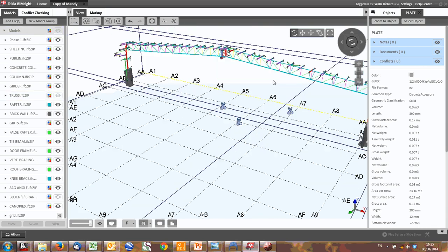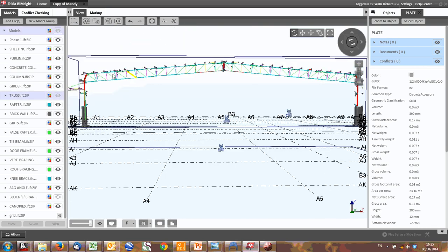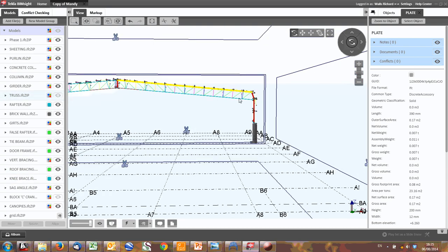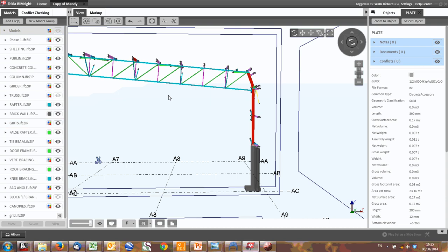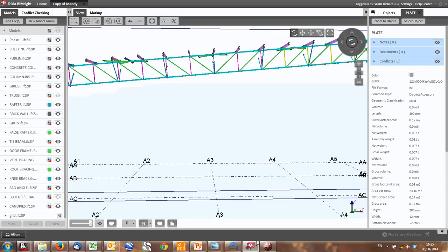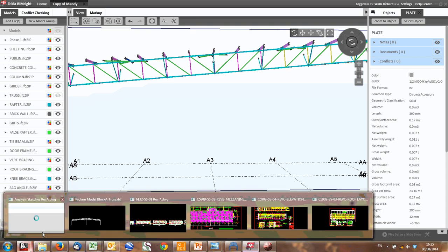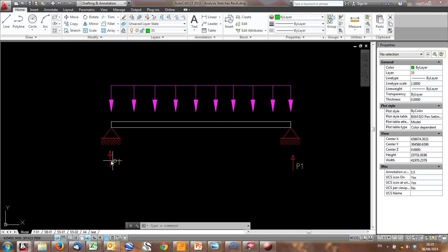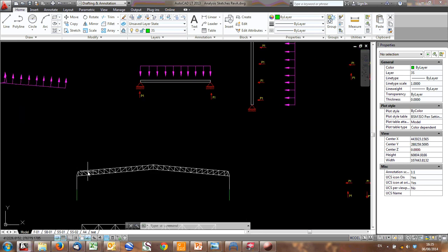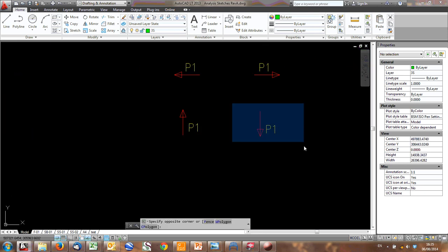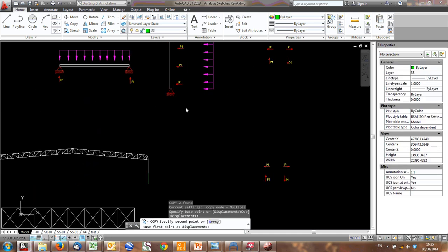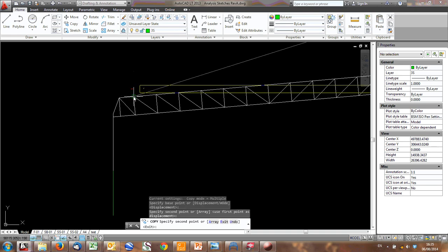Okay. So all these purlins sit on top of the truss. Purlin, purlin, purlin, and all down. And here you've got the girts, and those are supported by this truss. So if you have a look at this truss, let's go back here. This reaction now could actually be applied to this truss. So let's go put that on here. And this now comes down in all these different loads.